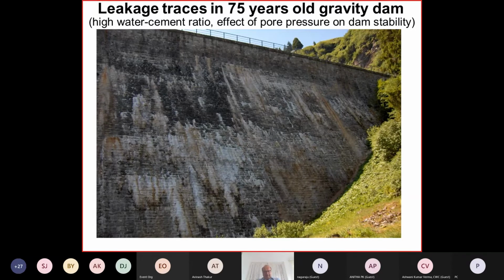We only have dense concrete, we cannot have a high water cement ratio. And here also the concrete becomes vulnerable to low temperature, so therefore the surface of this dam is covered by granite blocks, about 50 centimeters deep. So therefore, to protect, inside is all concrete. Only outside are these granite blocks. They are there for frost protection.